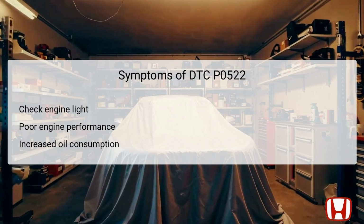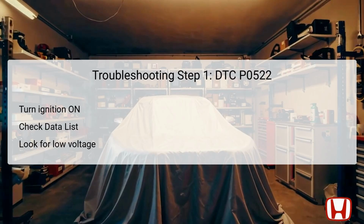The first troubleshooting step involves turning the ignition switch to the ON (II) position, enabling power to the vehicle's electrical systems. Following this, utilize the Honda Diagnostic System, HDS, to access the data list and specifically check the reading from the rocker arm oil pressure sensor. It's crucial to determine if the voltage is around 0.18 volts or less. If the reading confirms low voltage, proceed to the next step of troubleshooting.